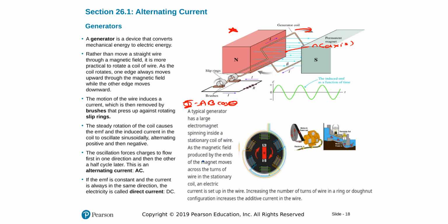And what this will cause is a current in one direction as it rotates in this fashion, and then it will change to the other direction after this point here. The current will turn in the other direction, and the same will go for the EMF. As I keep rotating, the change will keep happening, and here is a graph of the induced EMF I would have. It increases positive, decreases to zero, then increases negative, and so on and so forth. This is the idea used in generators.